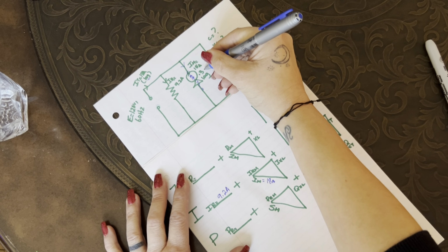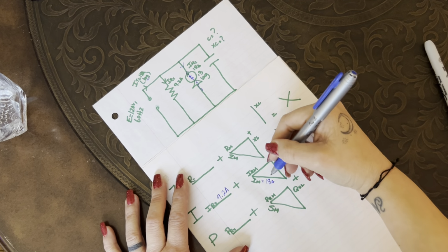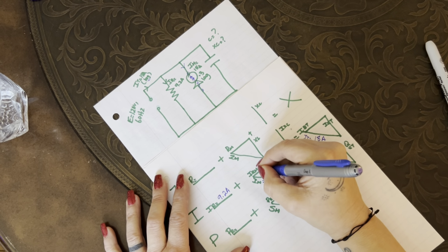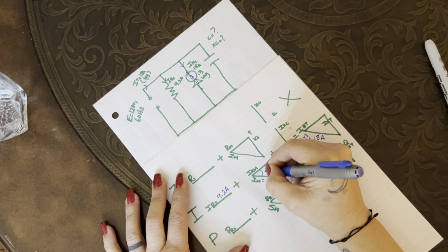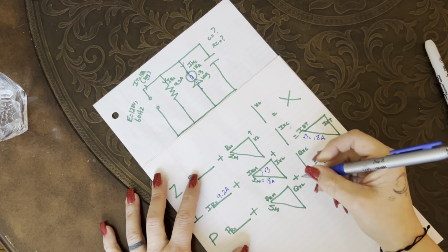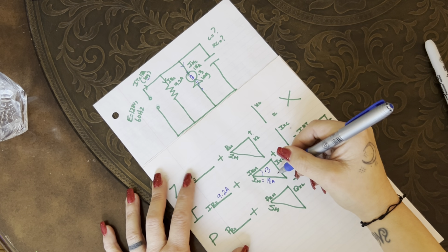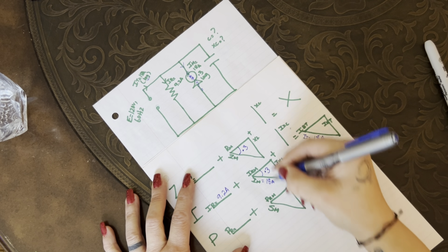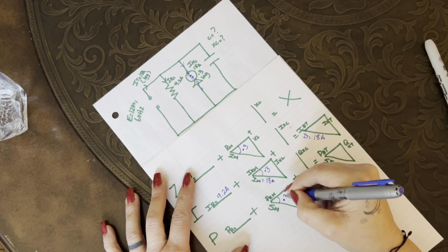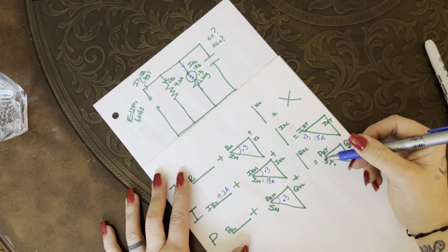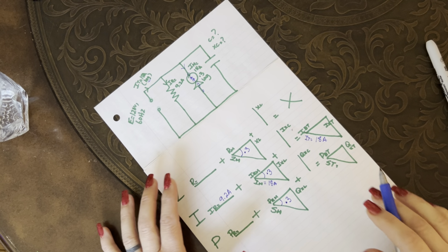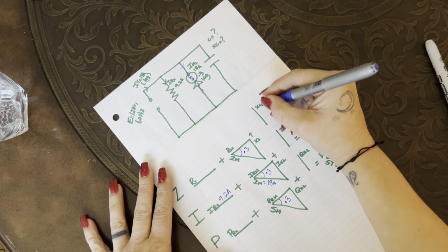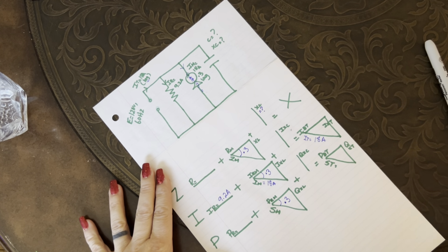Now they tell me the power factor, and that is the relationship between my in-phase current and my vectorial sum, right? So that's a 0.3 power factor. And I know if this is the power factor of my current triangle, that will be the power factor for all of my motor triangles, right? Okay. So now that's the motor information. I don't have anything on the capacitor. So now this is what I'm left to work with, and I need to dial back. Ultimately, I'm trying to get to here, all right?